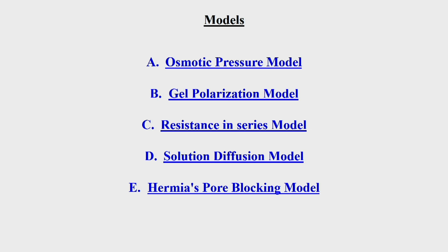The main objective of these models is that the effect of concentration polarization can be quantified using these models, and the flux decline profile and the concentration of the solute in the permeate can be predicted. If we want to design a membrane module or membrane reactor, then we need to do the theoretical studies. First, we will be discussing the osmotic pressure model.